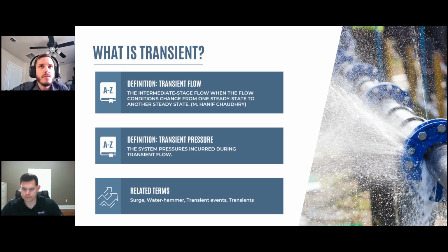So while water hammer is a phenomenon in the sense that it's a physical event, typically occurs outside of our perceived normal life, it's actually quite common and goes unnoticed most of the time. Whether we hear the audible hammer sound in the pipes or not, these pressure waves from any change in velocity are flying around in our piping systems all the time and can greatly vary in magnitude, and they can either be positive or negative.